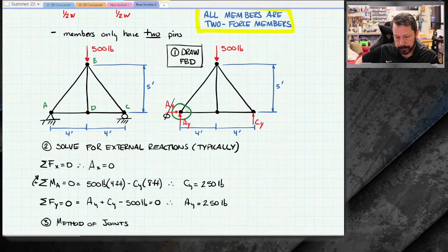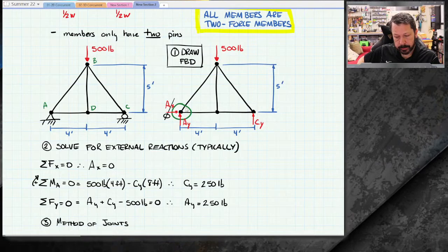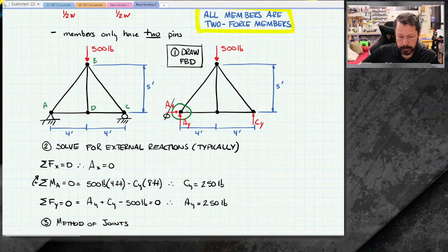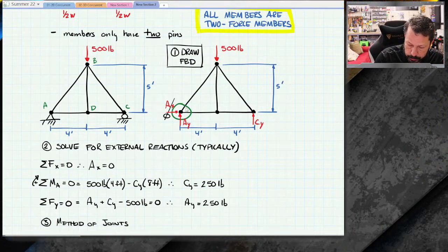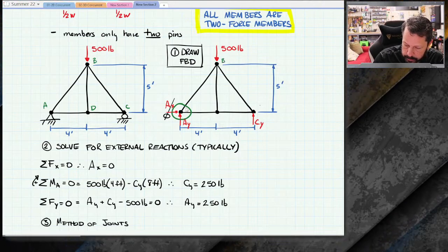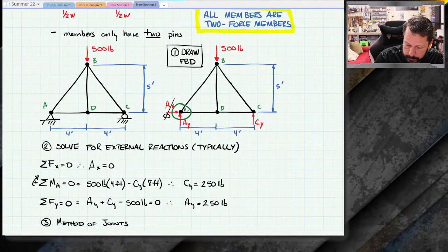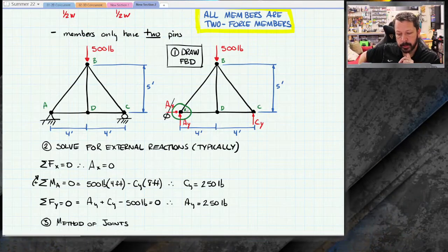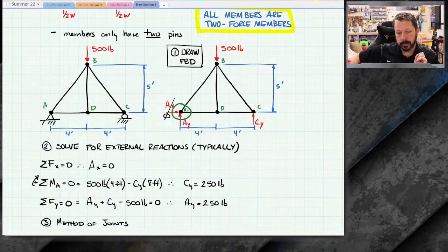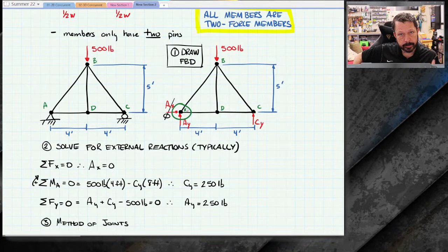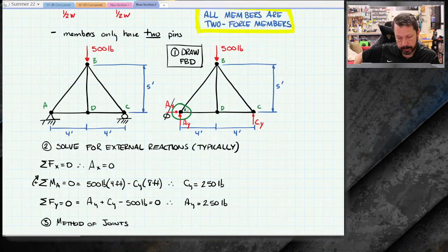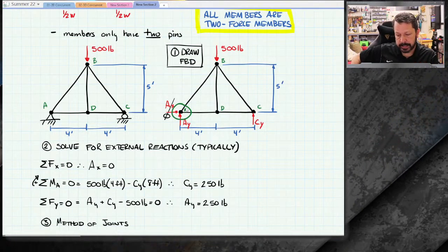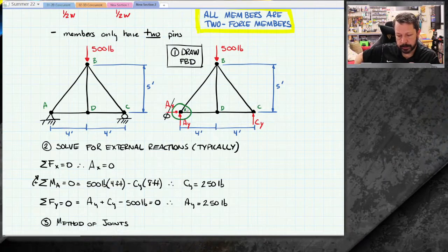And I would not know the value of member AB, and I would not know the value of member AD. But that falls into my rule. I have 2 unknowns and at least 1 known thing, so I could work from that one. Same thing with C. It's symmetric.